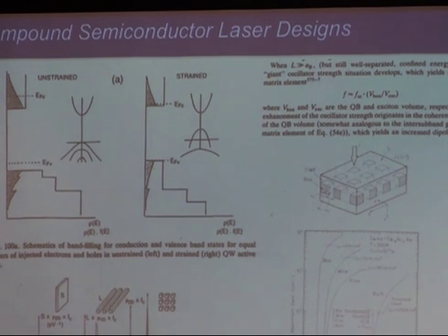But if you make a p-n junction, you're going to inject electrons and holes, exactly equal numbers of electrons and holes. N is equal to P inside. The injection into the quantum well is pretty much exactly the same for holes and electrons. As a result, the areas under these two shaded regions are the same. N and P are the same.